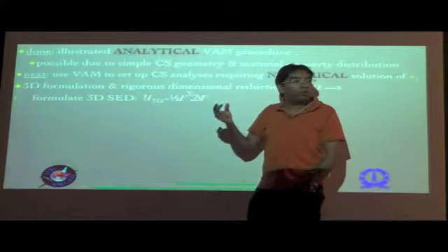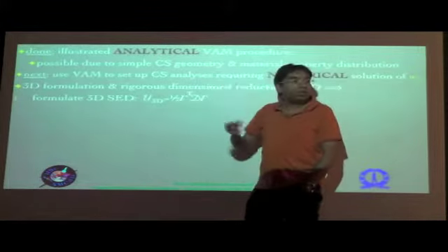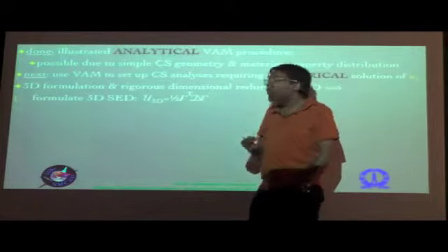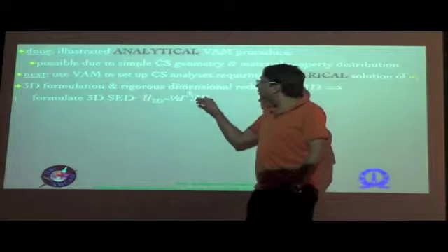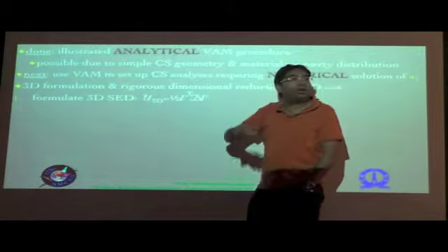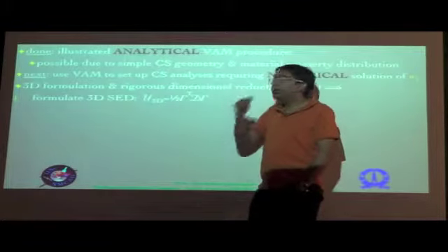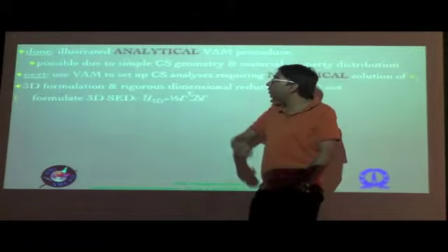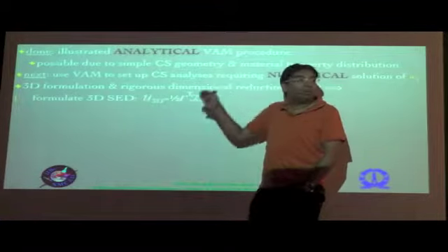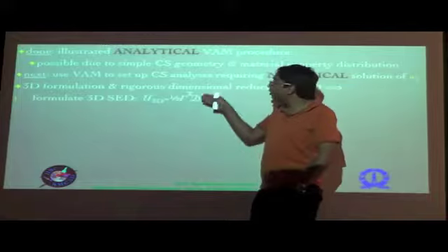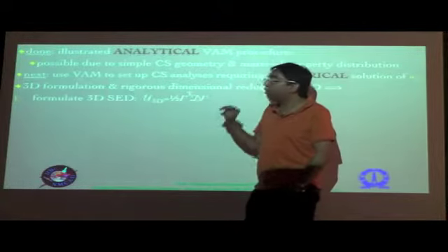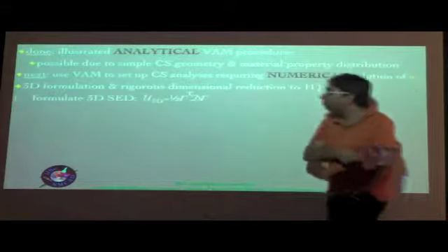D is a set of constants, but the D for the composite, as you know, is much more complicated and in general could be fully populated, and that basically brings about a difference, and of course it could have a layered configuration because of the plies in the laminate having different directions or hybrid composites, what have you, and therefore D not only will be fully populated but could also vary along the thickness direction. So these are the additional complications that you bring in to the picture.